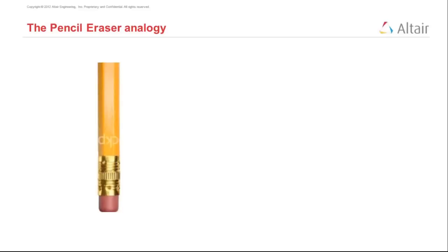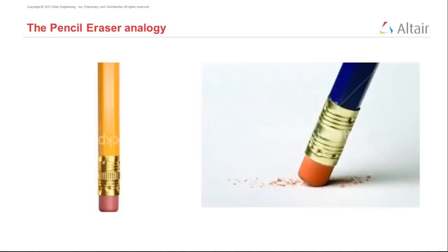This is a zero camber pencil with a rubber contact patch between the ground and the pencil. If you try and rub a sheet of paper, it is going to tear because the pencil is kept perfectly vertical, and the grip that the rubber produces on the paper is very high, and which actually ends up tearing the paper. However, if you tilt it slightly, even slightly, what you will see is that now the paper doesn't tear, but the pencil slides on the paper, which means introducing camber on the pencil rubber tip has decreased the amount of grip.